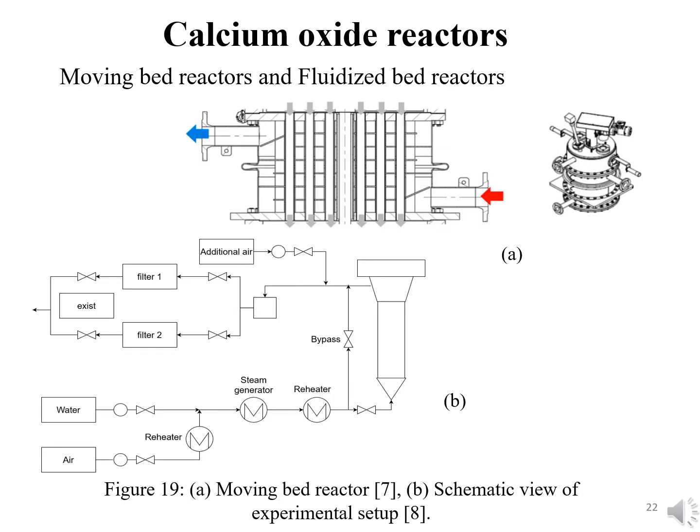In the moving bed reactor, the moving bed is believed to reduce the pressure drop and heat and mass transfer obstacles in a fixed bed. Diagram of the reactor is shown in figure 19a. This reactor adopts a counter current: unreacted material enters the pipeline from the top and hot air enters the reactor from the bottom. Heat is transferred by a hot fluid that flows on one side of the heat exchanger cell and is guided by a baffle. These plates ensure rapid air circulation.